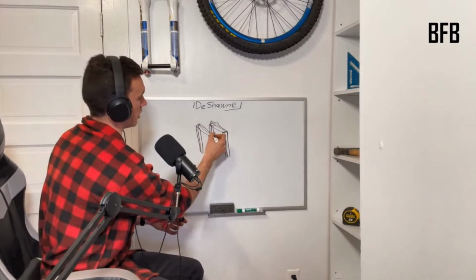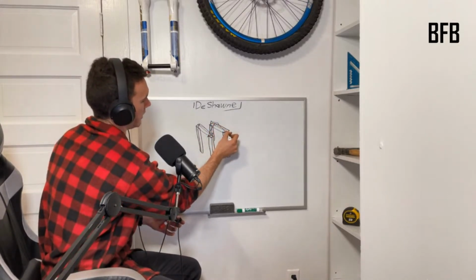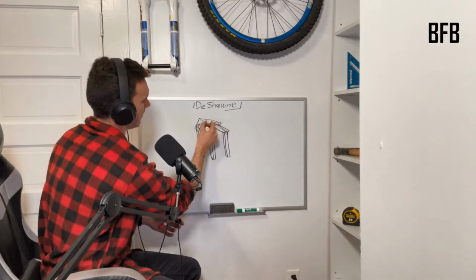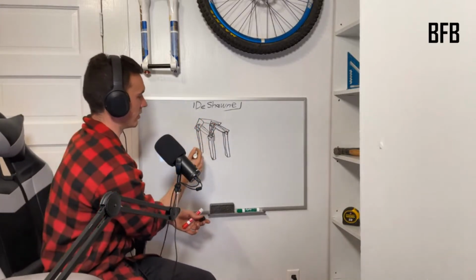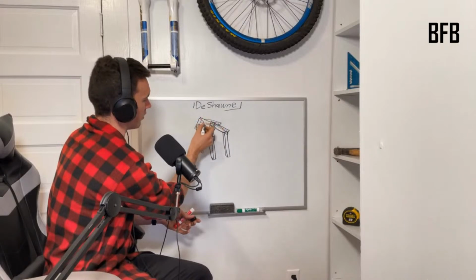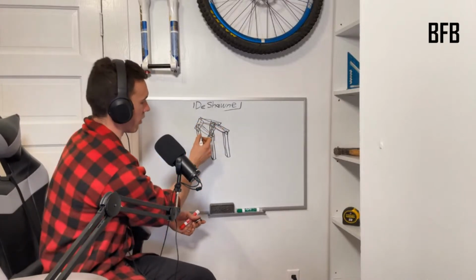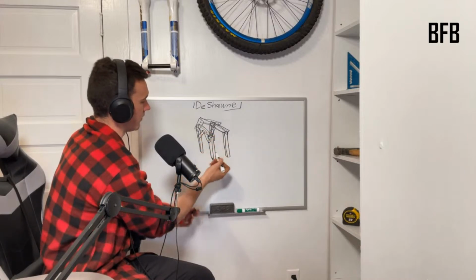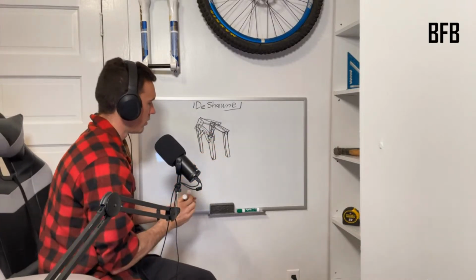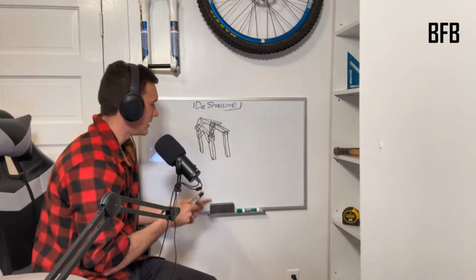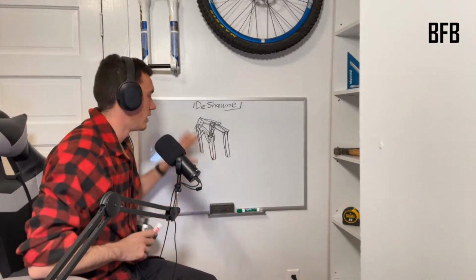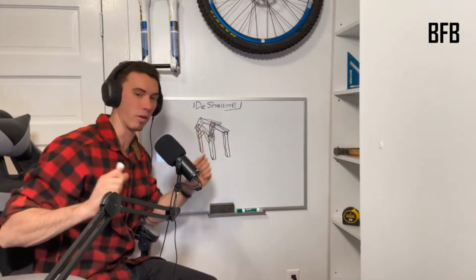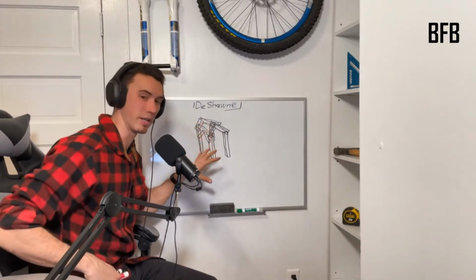And then you're going to take some other big chunks. And you're going to take those up at an angle and lean them against each other. Make some big chunky roof things. Yeah, like that. Okay. Big timber frame structure. And you're going to maybe put a big chunky one at the top for the ridge. All right. And then you might throw in some chunky angles, right? So the chunky angles are the things that give it this lateral strength. So the reason I'm talking about the whole timber framing is that when you have timber framing like this, the frame itself is designed with all the big chunks to resist all these lateral loads and all that stuff through all the members and their connections.